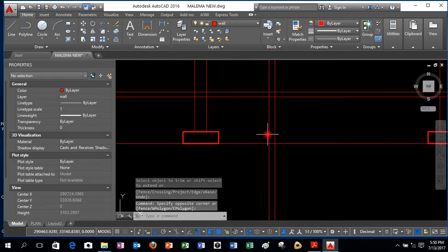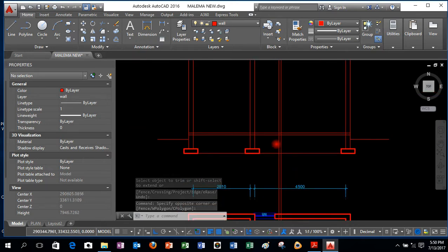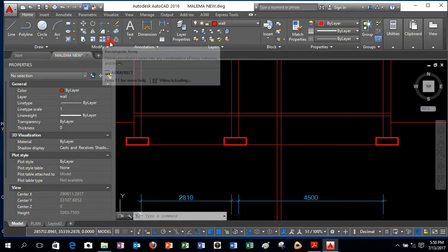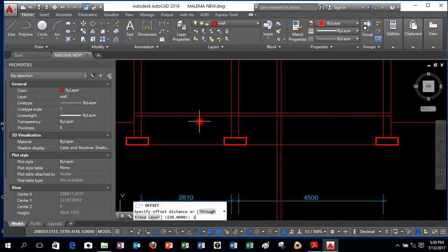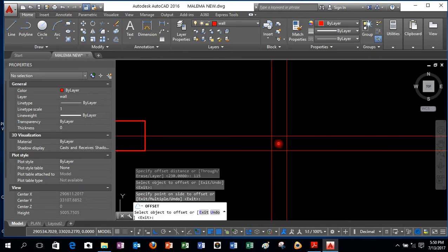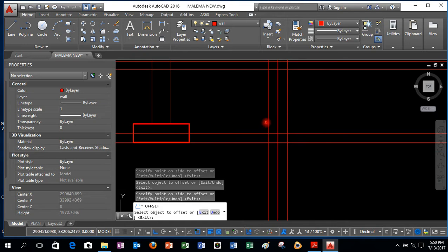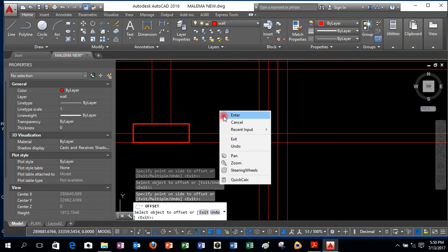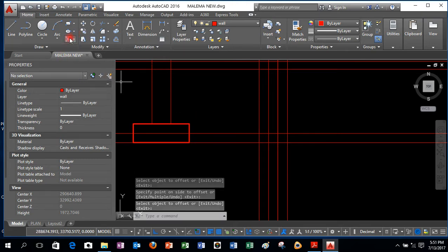the footing. Of course, for the internal wall, you can have its own footing. This is 115 millimeter thickness of the wall. Then the projections are going to be 115, and also the depth 115. So we have 115 this side, 115 that side. It's supposed to be 115 that side. I don't know what is happening, but it's supposed to be 115 this side. Yeah, so that's it. And then we can draw the rectangle.